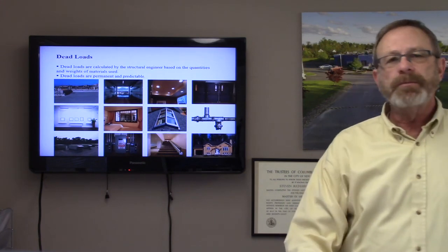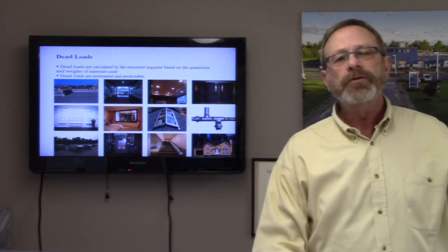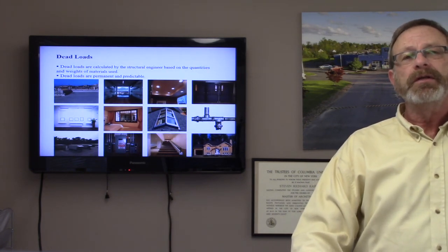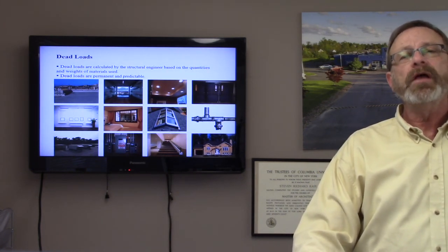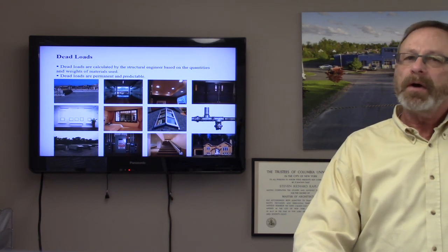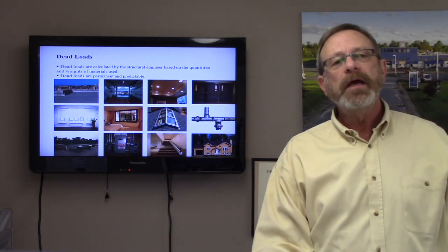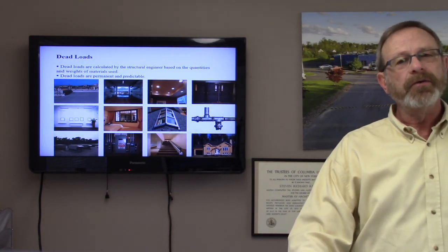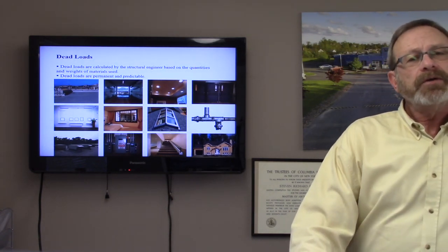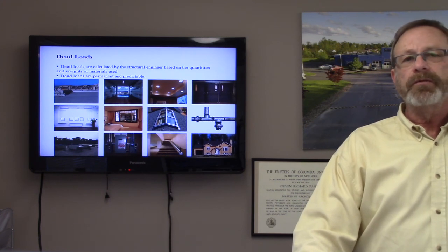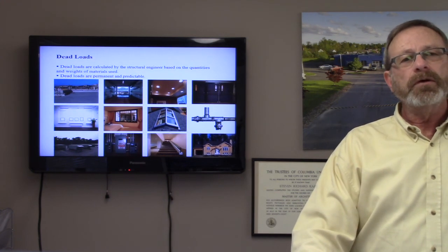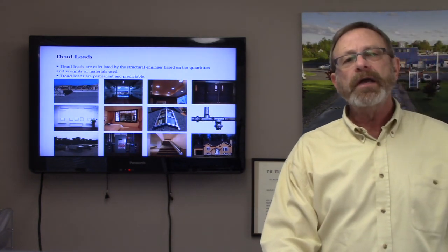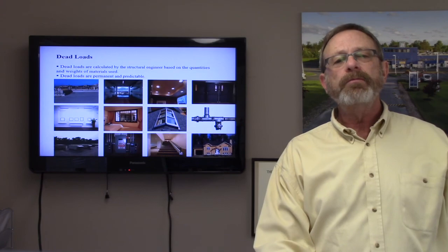We can see from this composite slide that the elements of a structure can add up quickly and to a heavy load. The evaluation of loads is a careful and painstaking job. No one wants to fall through a floor because the engineer had made a mistake in assessing the weight of the people expected to be there, the live loads, and objects on the floor, such as furniture, desks, chairs, and the floor weight itself. For these reasons, engineers generally overcalculate to assure a healthy margin of safety.